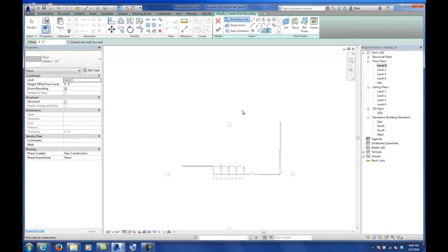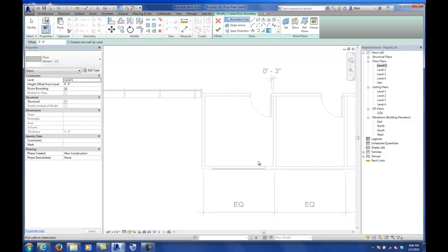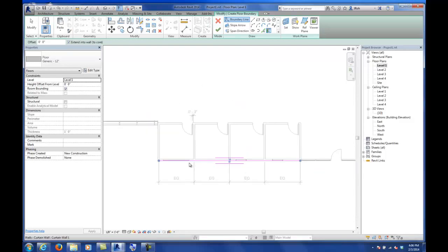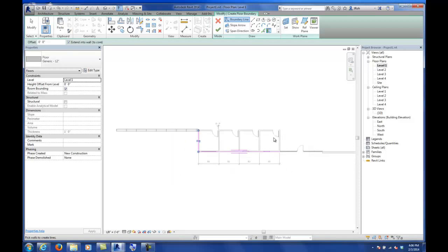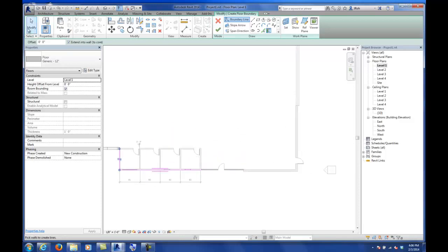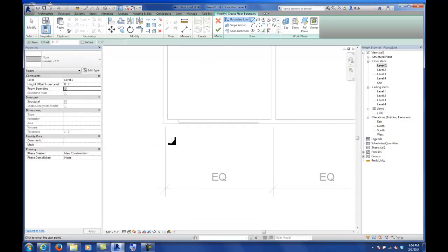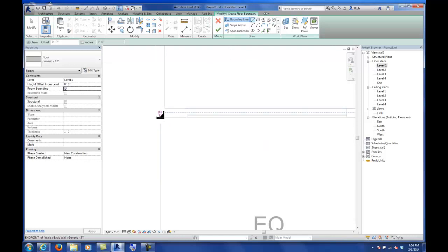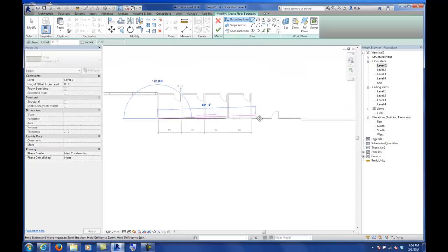I'm going to use my walls. There's this little pick walls command. And I can tell it to essentially pick my wall and then draw a line. So it's basically drawing to the edge of that wall. And just go around, and if I have walls drawn, I can go ahead and do that. Or I can just draw with pick lines or just a regular drawing command. And I'm going to go ahead and just trace what I have already.